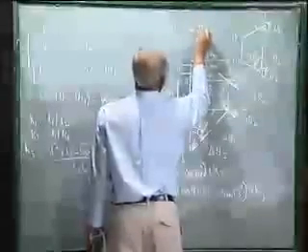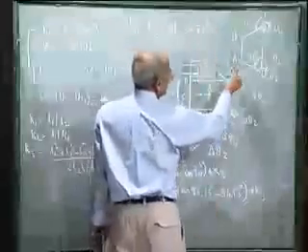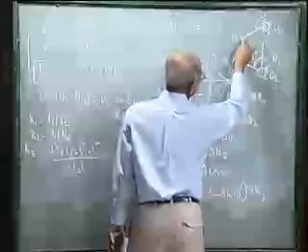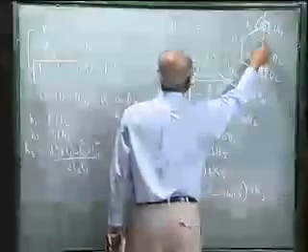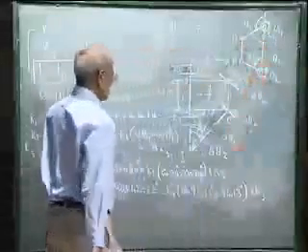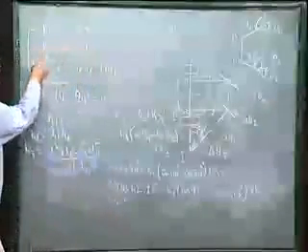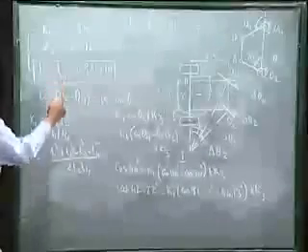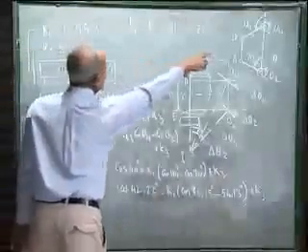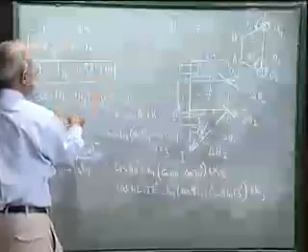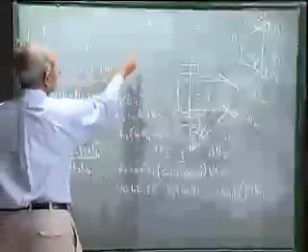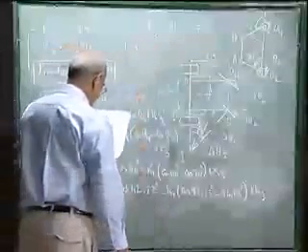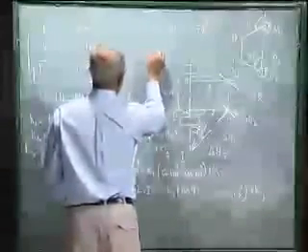cosine 70 degree. L2 cosine 70 degree plus L4, which is same as L2, this is also 70 degree. So again L2 cosine 70 degree plus L3 is L1. I can either solve it from this value of K3, because I know already L1 and L2, L4, I can find L3, or I can directly use L1 and L2 which I have obtained to find the value of L3, which will turn out to be 1.17.